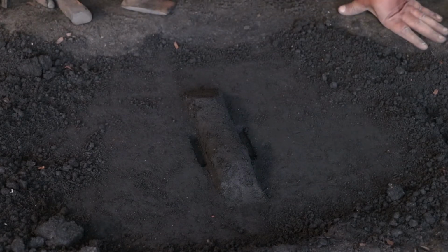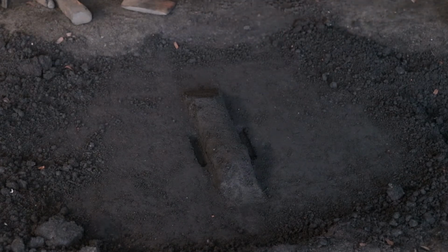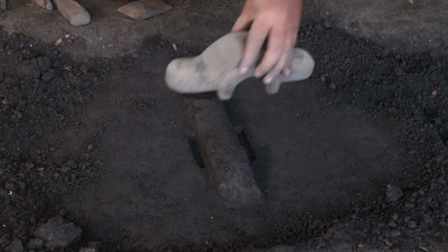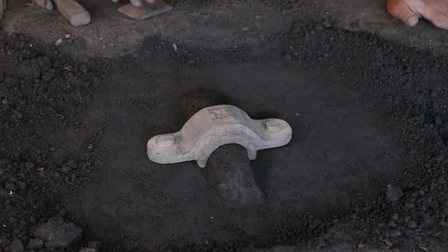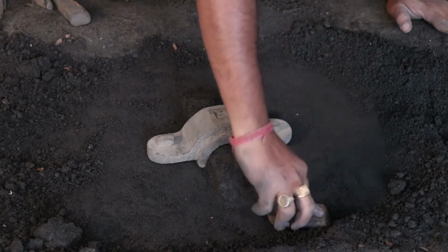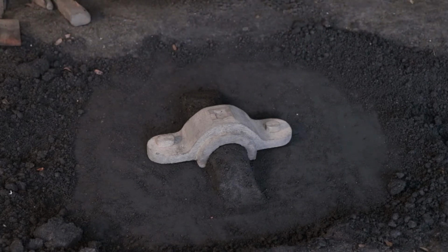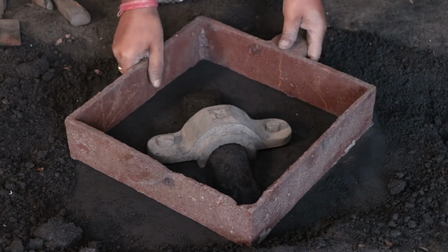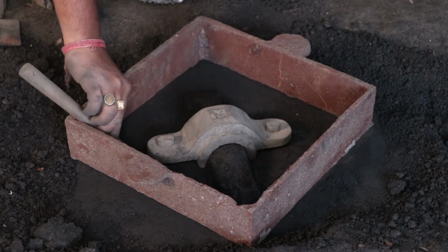Now, as you can see, the core has been completed as you are working on green sand. So this is known as a green sand core, which will help us complete the entire operation of this plumber block cap. After completing the entire thing, we are placing this pattern once again. Need to plane out the area. This is your cope. We are placing a cope again. Your runner and riser. This is the runner that we are placing here.